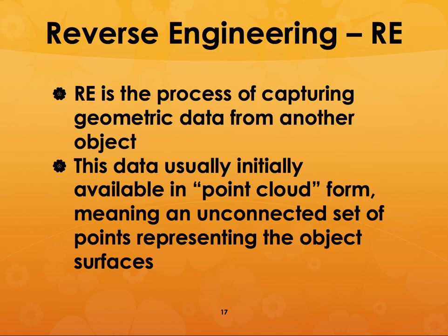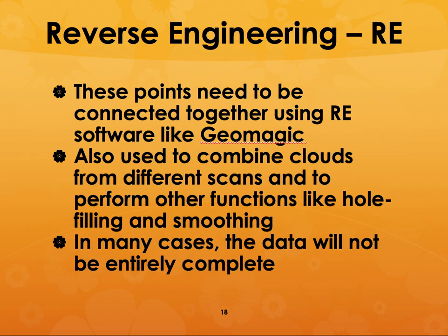So reverse engineering is the process of capturing geometric data from another object, a broken part, and it is available in what is called point cloud form, and it is an unconnected set of points representing the object surfaces. So you are only going to get the surface and not what is inside, and you will have to define that by manipulating the data and creating the CAD model itself.